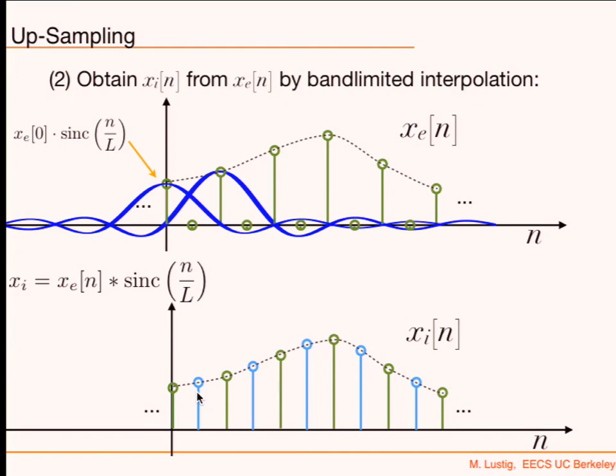Yeah. I'll get to that in a second. That's a really good point. Right, I could have done a linear. I could also do the zero order hold. Right, nearest neighbor. Right, I can do spline. All of these are going to have certain implications about what's going to happen to your signal. Okay, and there might be better ones than doing this.